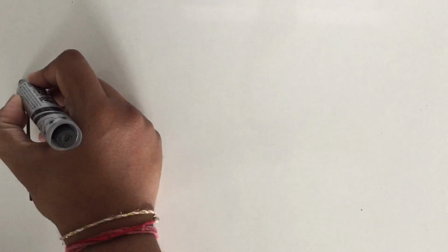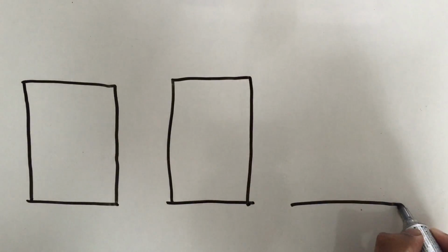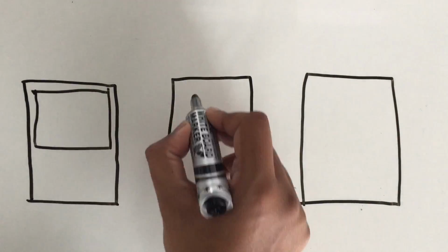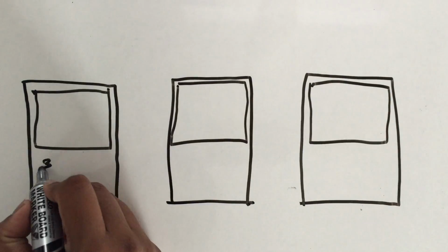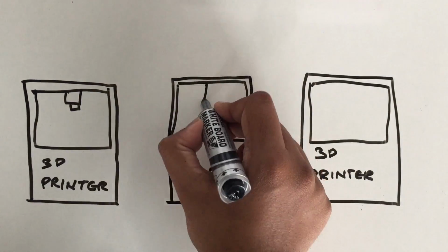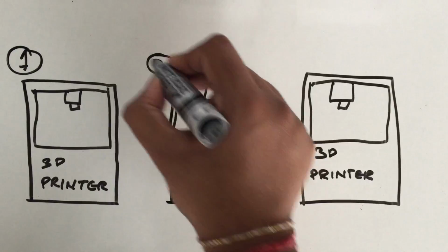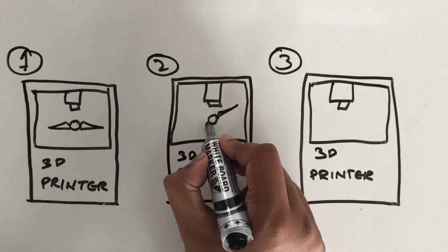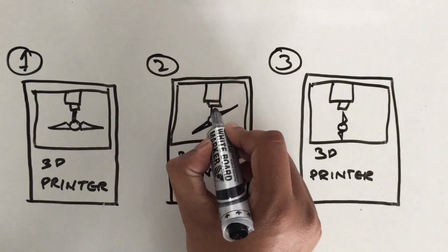The manufacturing process was completed in 3 parts. Firstly, the entire blade, including the hub, was 3D printed. While simple in principle, the printing direction is an important consideration since different directions have an effect on the surface finish and structural integrity of the blade, especially at its thinnest regions. This led to our design being printed 3 times in order to ascertain the best printing format.